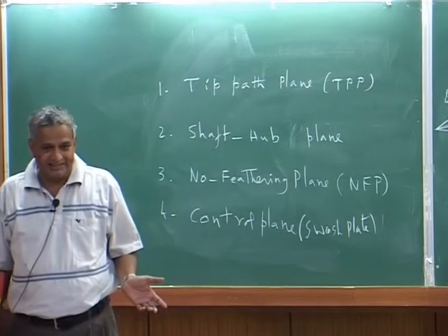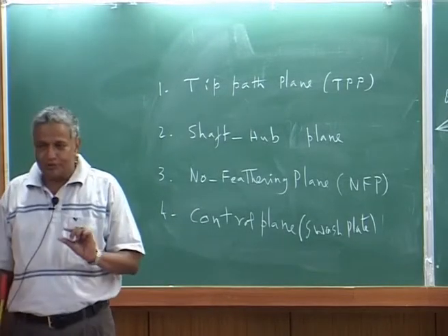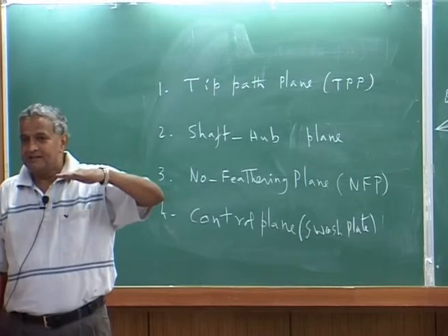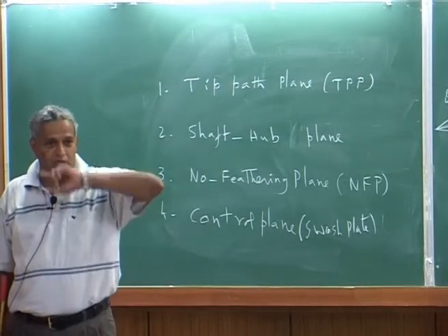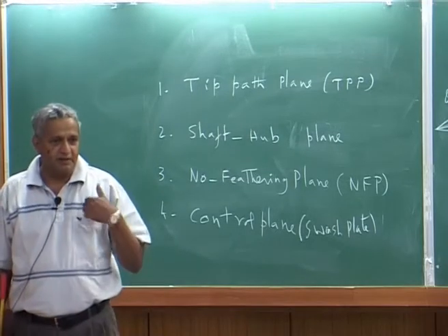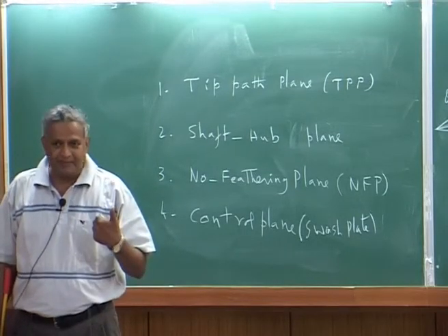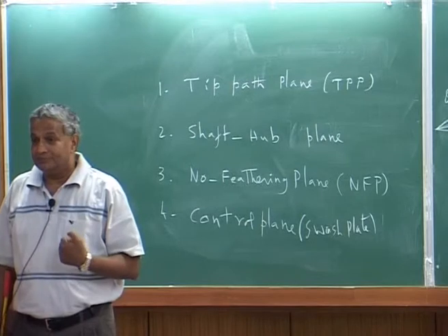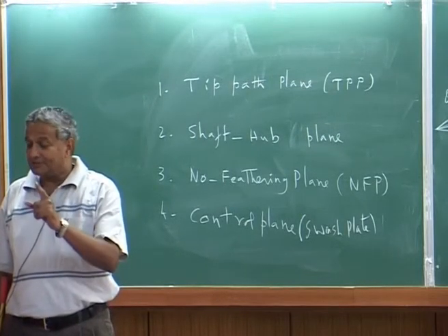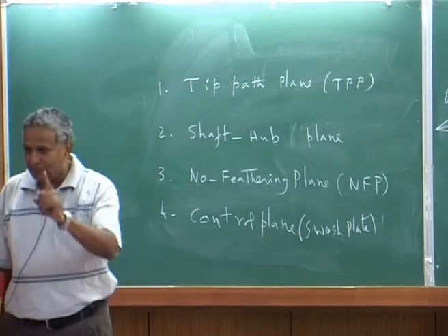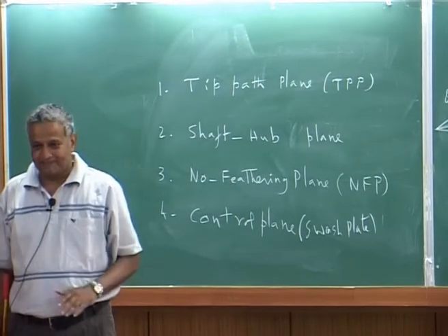You understand? Now we will use only hub plane. Now the whole point goes, okay, what is my advance ratio, what is my inflow, okay, everything is referred with respect to hub plane, okay.